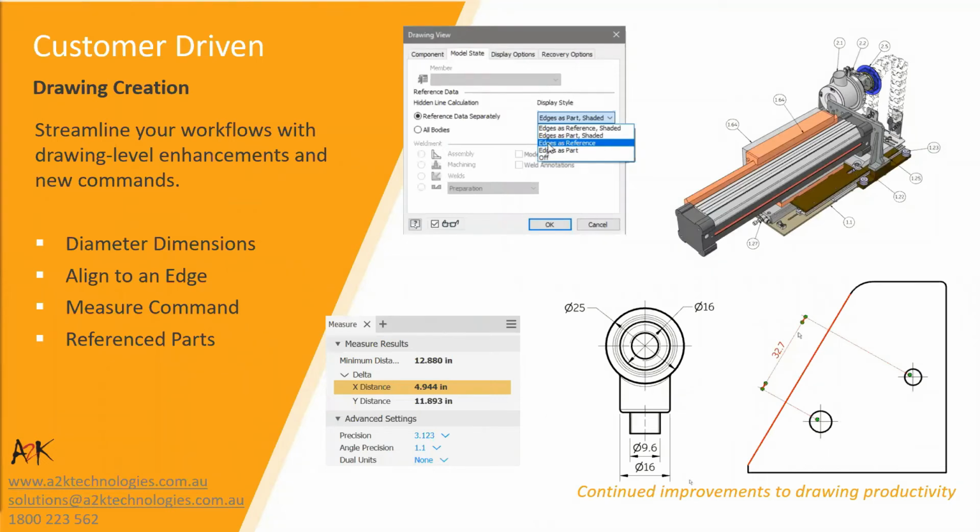The drawing view dialog box is enhanced to allow you to create shaded views of reference parts. The line style settings section is renamed to display style and updated to have two new options for creating shaded views of a reference part, such as edges as reference shaded and edges as part shaded.